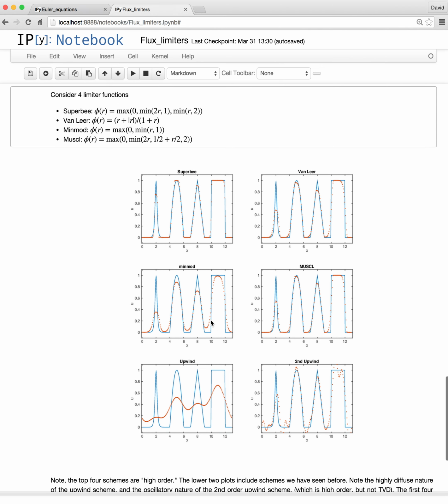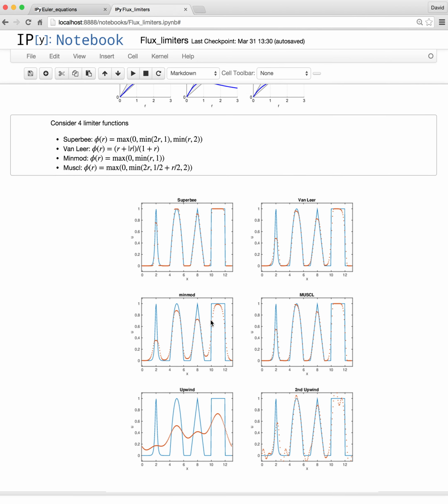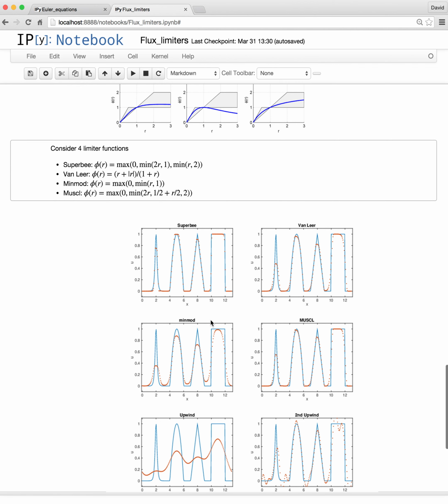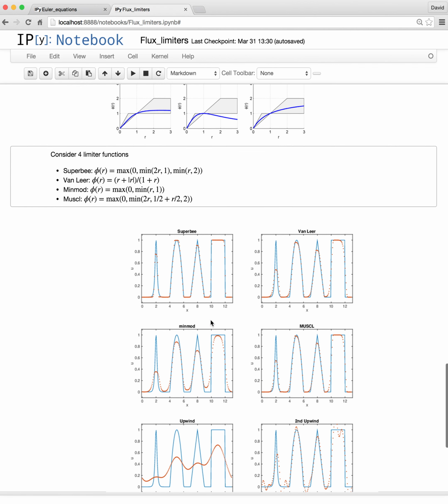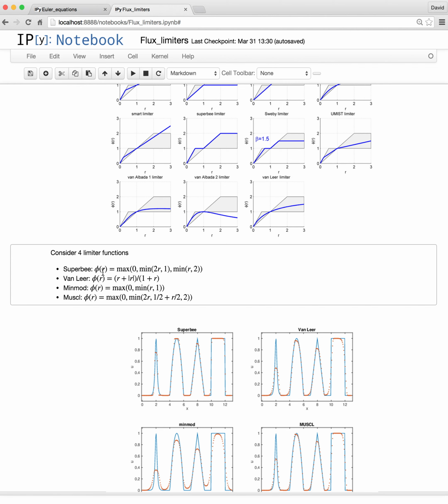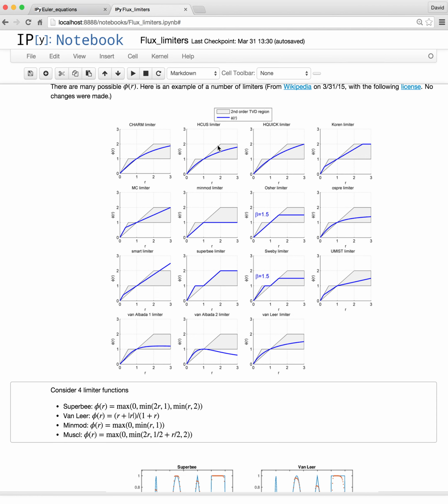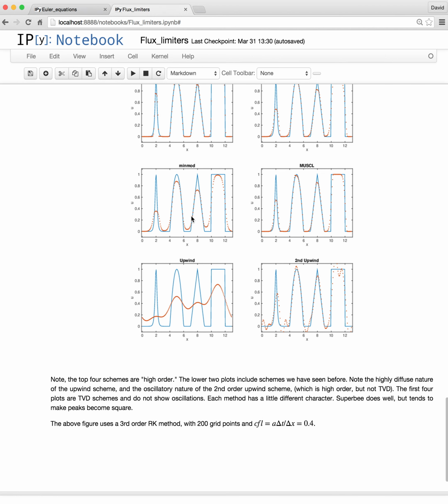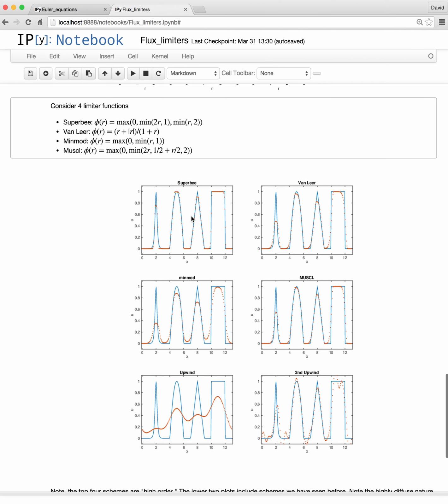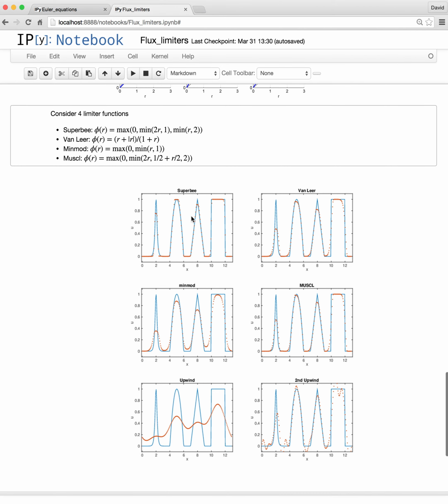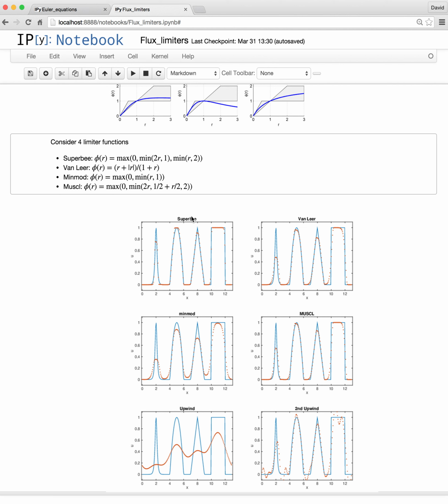And so which method you choose depends a little bit on the problem type you have, and it's pretty easy to change methods. You literally just code a one-liner in your code will change the function that you evaluate, and you can go on with those. So these are really popular to use in all kinds of CFD applications where we have convective terms in the equations, and we'll often evaluate the fluxes using these high order flux limited schemes.